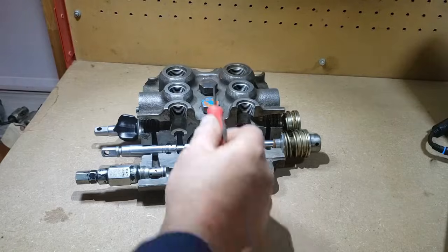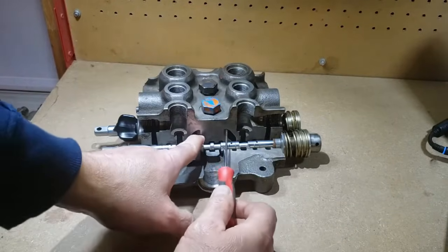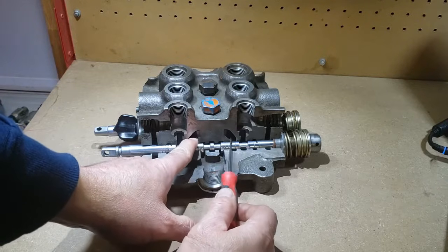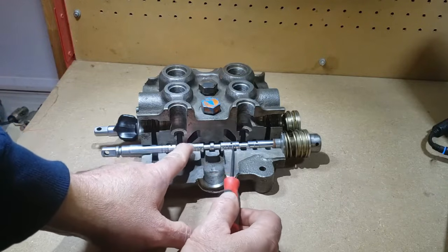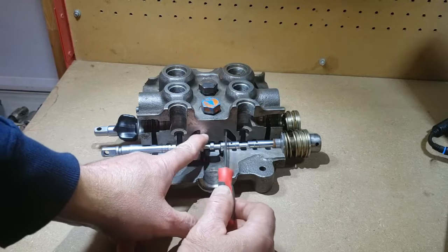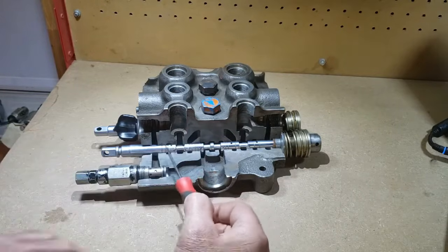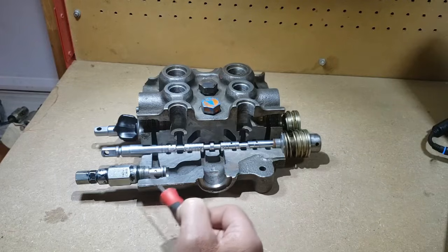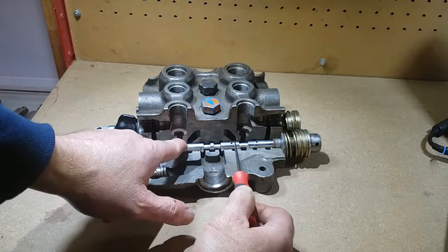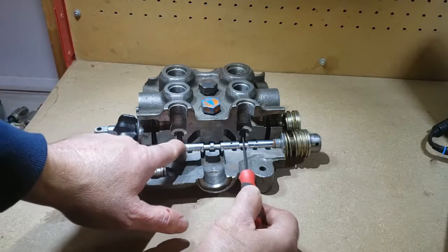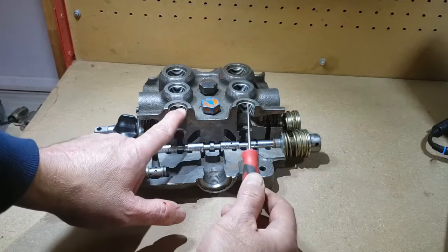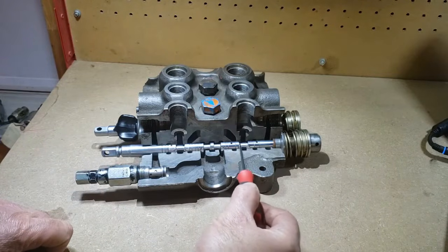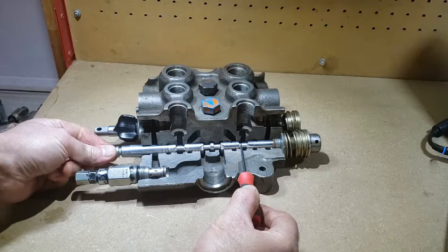We basically have the open center flow path through the center. Then a little further out, we've got this sort of bridge passage or parallel feed passage that comes down and hits the spool in two places again, which you can see when this is machined open. There's a little more to it, but it's sort of machined off at that point. And then outside of where the bridge passages land at the spool, we've got the work ports. So here you can see the work port for the head end of the lift function, and it's blocked by the spool because this is a cylinder spool.